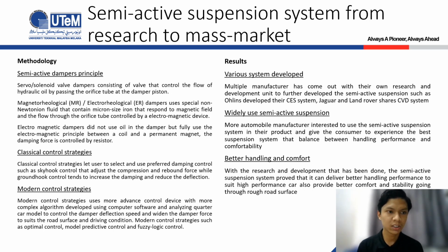So we'll go through the semi-active dampers principle. Basically, the dampers principle contains three principles, which is servo and solenoid, magnetorheological and electrorheological, and also electromagnetic dampers. So for servo solenoid valve dampers, they consist of a valve that controls the flow of hydraulic oil by passing the orifice tube at the damper piston.